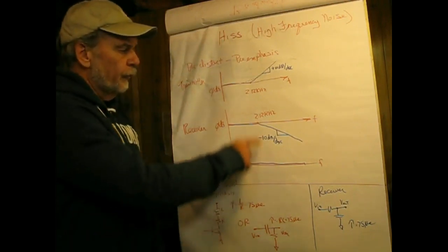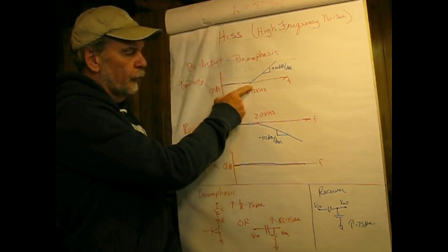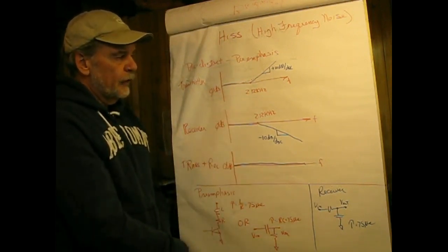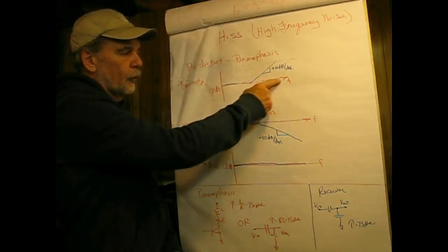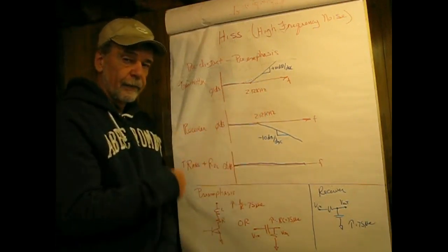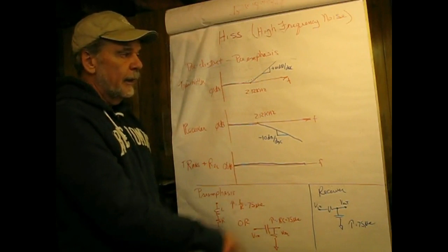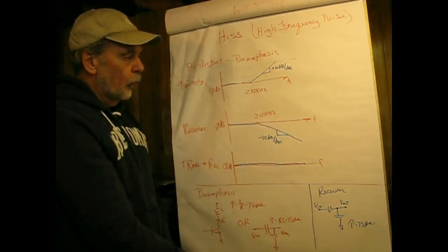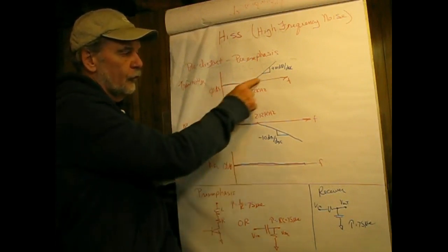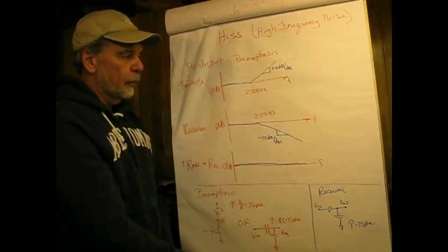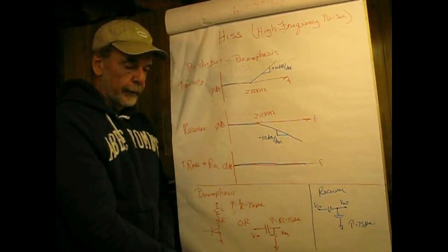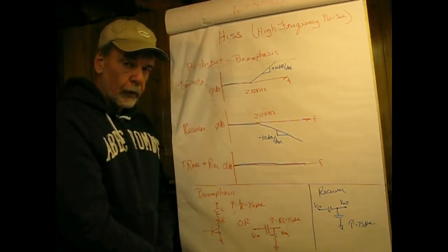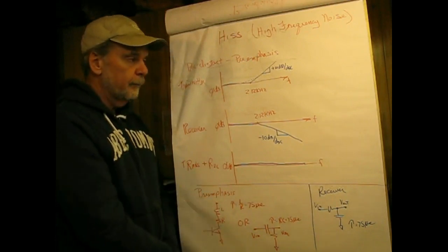It was found that a frequency, 2.12 kilohertz, was a good corner frequency. And what happens after that is any frequency components in the speech or music get emphasized, that means increased, at a rate of plus 10 dB per decade. So if we were to listen to this out of the preemphasis network, the higher frequency components, like the sound of a cymbal on a drum, would be too loud relative to what they should be.